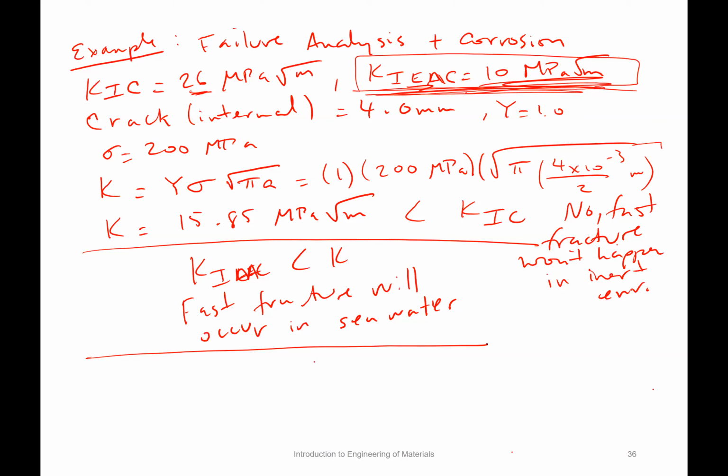Oh yeah, so that's just to take into account the galvanic series, in comparison of whether a material is more or less active. And correct, that does not have to do with the passivation layer per se. I think what you're referring to is the native oxide passivating layer that typically forms on zinc. So you'll always find maybe a few nanometers of zinc oxide on zinc if it's just left alone and you haven't reduced it. And then, yeah, same thing with aluminum.